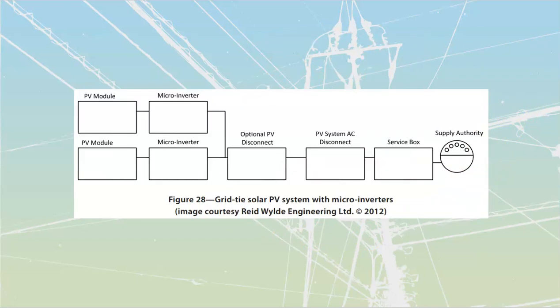Smaller ones that I'm going to use will have microinverters. Microinverters are going to be on the roof itself. So I'm going to have the actual photovoltaic array that plugs directly into the microinverter. Note that I don't have a combiner box over here. This micro array is just going to be synced up.